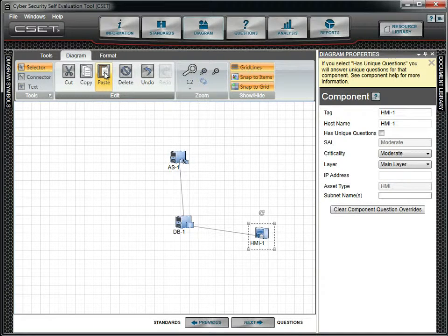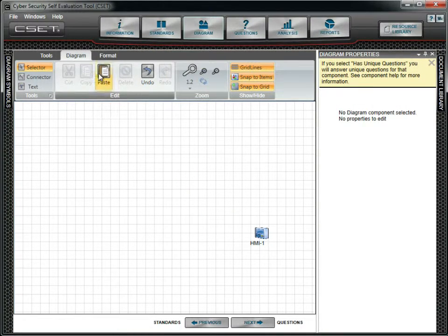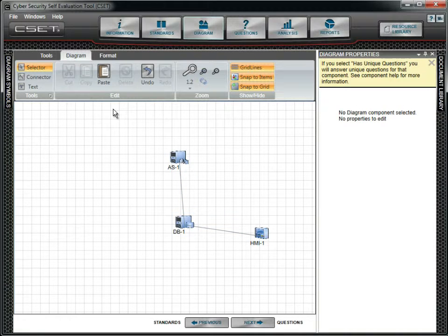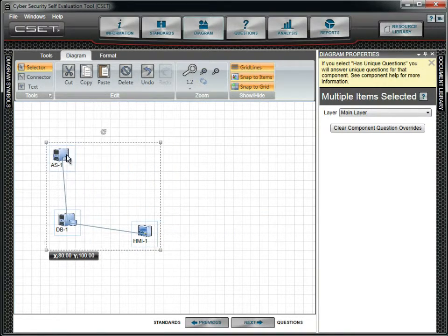The HMI is created. By selecting multiple components and the line in a selection frame, we can cut and paste both the components and the connecting line. This is especially important when doing a copy and paste, which we will do next. To copy one or more objects, you will need to first select them individually or as a group. You can select objects by using a frame or by selecting them one at a time with the mouse and the Control or Shift key depressed. This is consistent with how most Windows programs work.